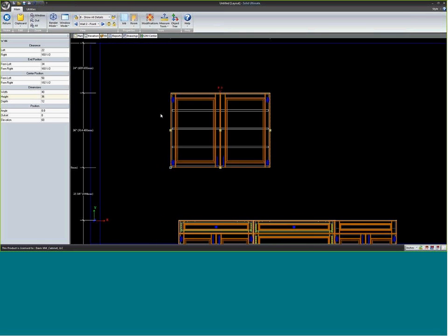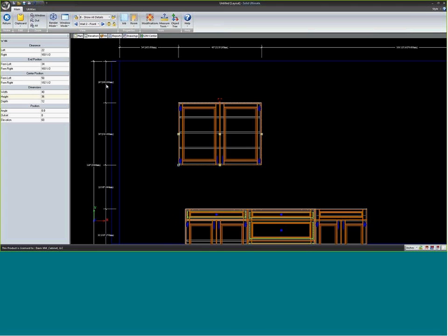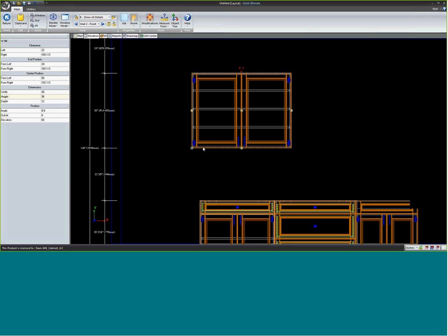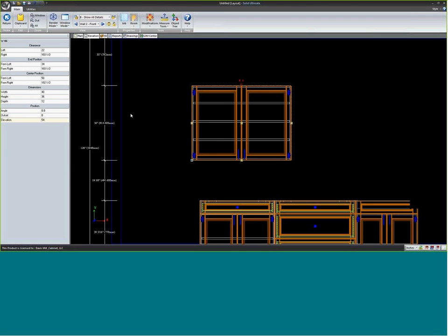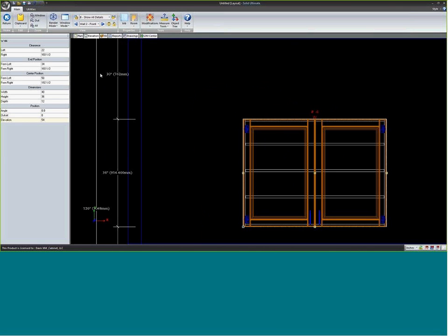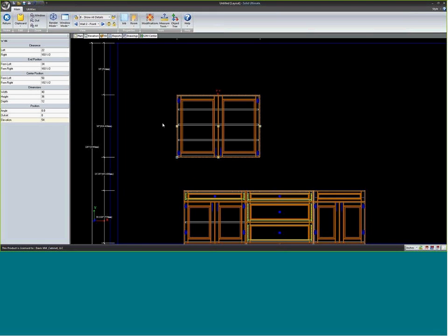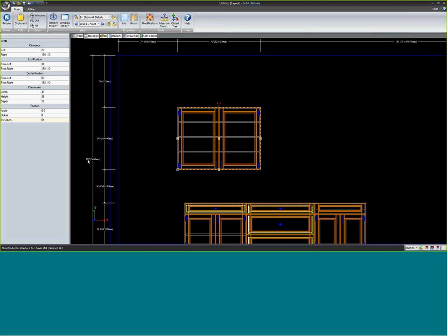Now, on the height of a wall cabinet, remember before I talked about the soffit height being where it snaps to? We know that you're going to have a certain height that your wall cabinets are going to end up being. In this case, I probably should have had a 30-inch soffit height rather than a 24 if I get a 54-inch clearance. What I want my clearance to be, though, I can do the math here. 120 minus the standard height of my wall cabinets, in this case 36 inches, minus my 54 inches, and that would give me my soffit height.